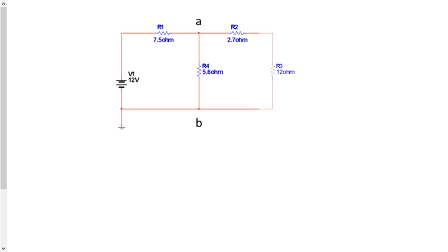We had another question with a more complicated circuit like this. You know, we've kind of done this already. This is a little bit simpler than the one that we've done. But you'll have to simplify this and work your way towards the 12-volt battery. You can start out by recognizing that this part's a series, and that's a parallel, and that's series. So we trace electricity out. It goes this way. Must go through this resistor. And now has this branch to go through, and then this branch to go through. But go ahead and simplify it.